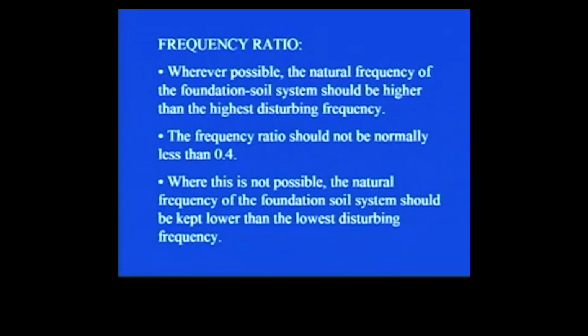Then some of the guidelines related to frequency ratio. Wherever possible, the natural frequency of the foundation soil system should be higher than the highest disturbing frequency. As you know, to avoid resonance, the operating frequency should not be equal to the natural frequency of the soil foundation system.